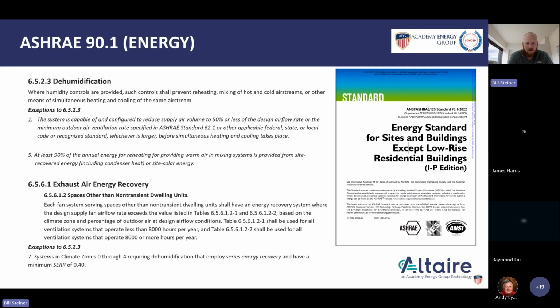The two that we'll talk about are the two that are applicable to this technology, and that is exception number one. And essentially, what exception number one is saying is if you decouple, if you're only doing that simultaneous cooling and reheating to 50% or less of the airstream, aka just the outside air, then you're allowed to do that simultaneous cooling and reheat because it is much more efficient to only apply that to the minimum outside air requirements.